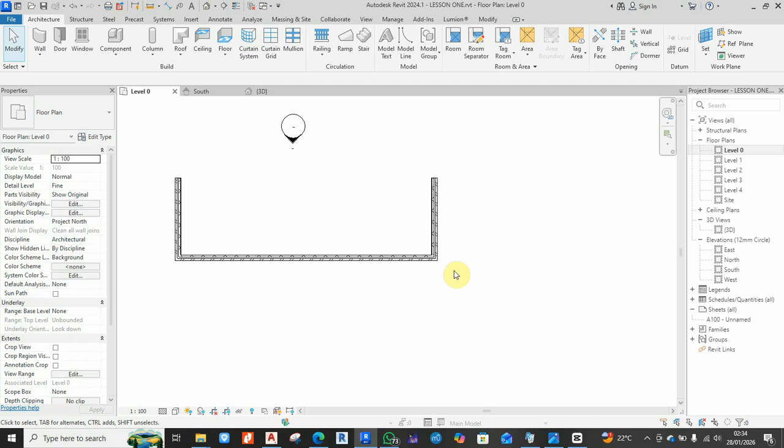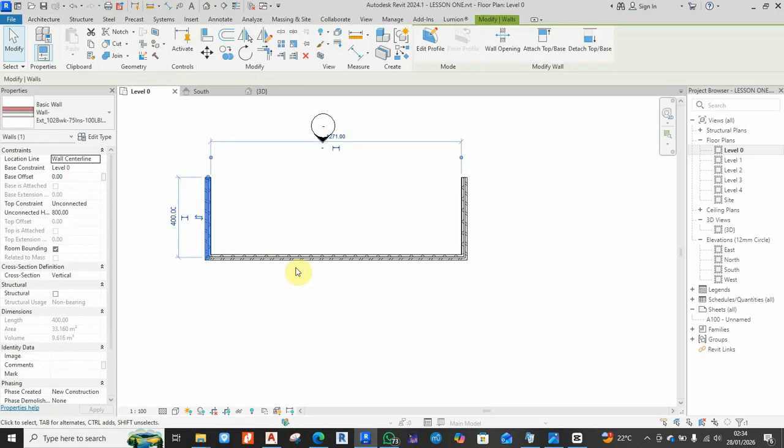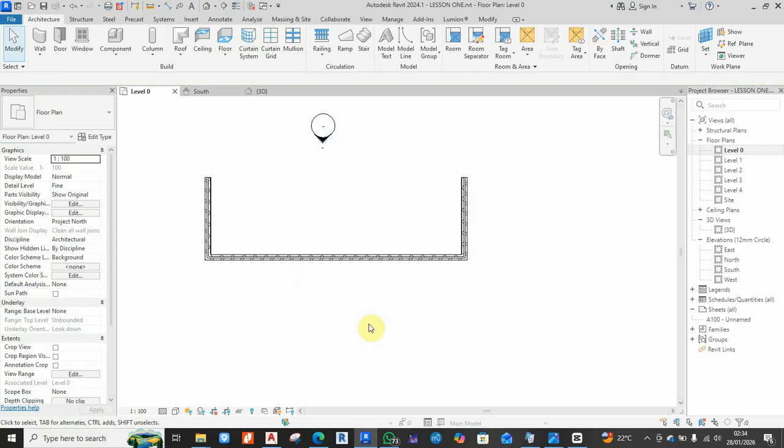God bless you all. So, like I was saying, you can select individual elements. Now, the third method of selection is highlighting from right to left. So, if I click my left mouse button, and I hold and I'm dragging, you see the selection box in dotted lines appears.